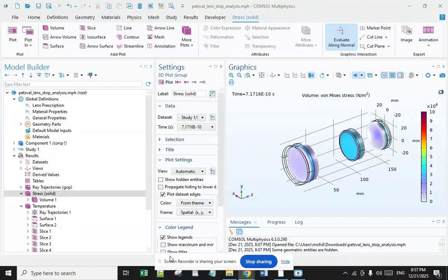Though the maximum vacuum one can theoretically achieve at sea level is 29.921 inches of mercury, Hg. This will vary significantly as altitude increases. For example, in Denver, Colorado, at 1 mile, 1.6 kilometers above sea level, it is only possible to achieve a vacuum on the mercury scale of 24.896 Hg.